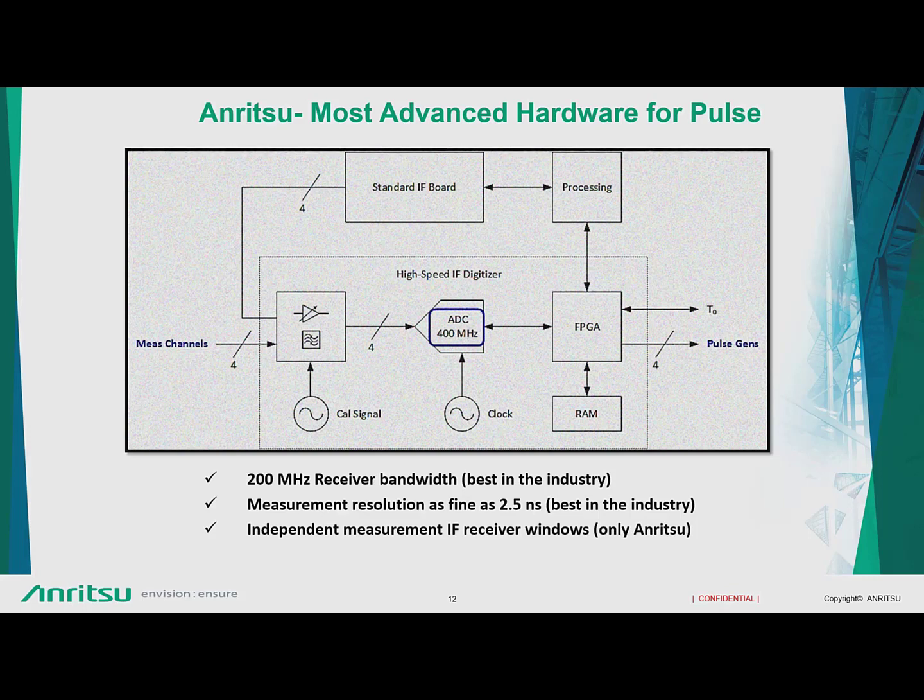As I told you initially, if the device under test has some delays associated with it, and it has an input and an output port, and the transmit side pulse goes in and takes a long time to reach port 2, the two receivers are out of sync. When they are out of sync, the S21 or ratio measurement can be affected, and I'll show you how that is very important.